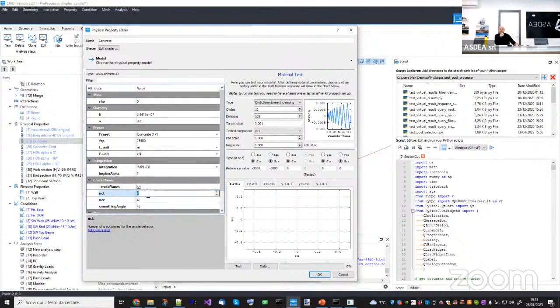Okay. So if you have 4 subdivisions for 90 degrees, I have a unit sphere. Due to symmetry, I have twice that one, but it is in 3D. So for 4, I think it was 8 by 8. If you increase that a lot, you can rapidly go to thousands of normals, and then at each iteration you have to find what is the closest normal. So my suggestion would be 4 normals are fine. If you want, you can put 8, but if you exaggerate here, the cost will grow a lot. So don't do that. But it's not even necessary, because taking a spacing of like 20 degrees between each crack is more than enough.